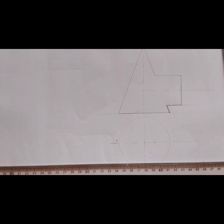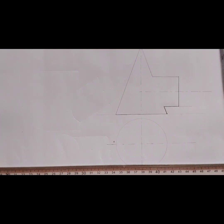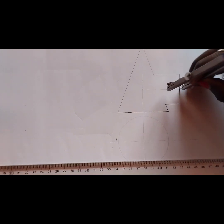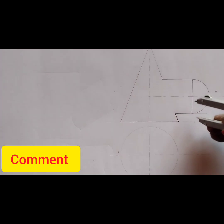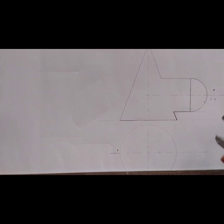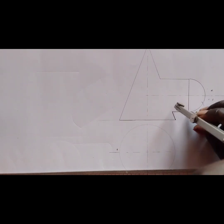From there, we're going to draw a semicircle on this other end. And remember, we've been told that the diameter of our semicircle is 40. So I'm going to open my compass to this other end and draw a semicircle. So that is my semicircle. I'm going to divide this semicircle into 6 equal parts.